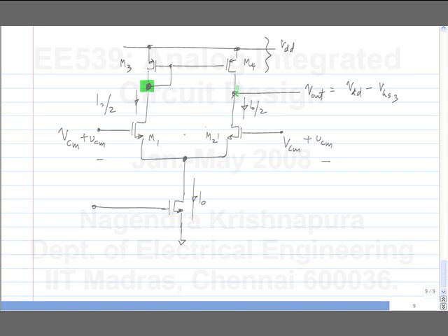If the left side drain voltage is different from the right side drain voltage, you will get an inconsistent condition. The NMOS analysis will say that one current is more than the other, and the PMOS will say the same thing is less than the other one. So, the two have to be equal. So, this we already know. All this makes the analysis very easy.